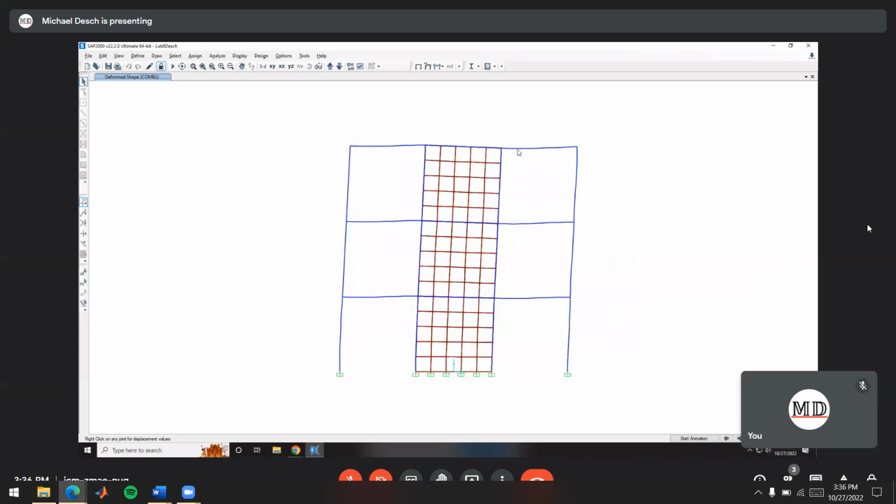So we can kind of see the behavior of what's happening in the structure here. Our shear wall is basically acting like a very, very stout column that's basically cantilevered from the ground here. So it's got that just single curvature bending like that. And all of our comparatively more slender elements here usually have that type of bicurvature around them when they're fixed to our frame like this.